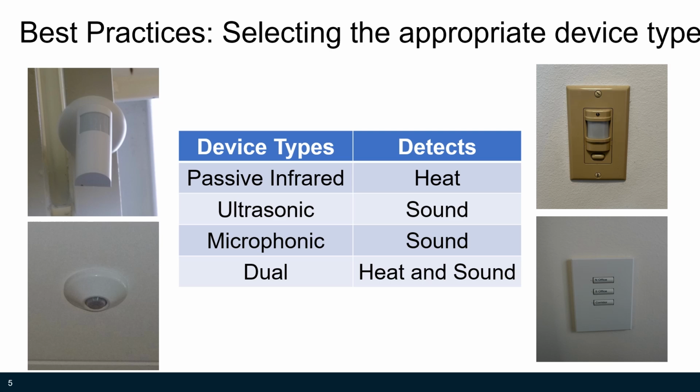Lighting practitioners are knowledgeable on how best to apply the various sensing technologies. For instance, a technology that does not rely on direct line of sight, like ultrasonic, is essential for proper function in spaces with tall partitions, like toilet rooms or open offices. Ultrasonic, on the other hand, can be problematic in places where higher HVAC airflows are likely to trigger false occupancy, keeping lights on when a space is actually vacant.